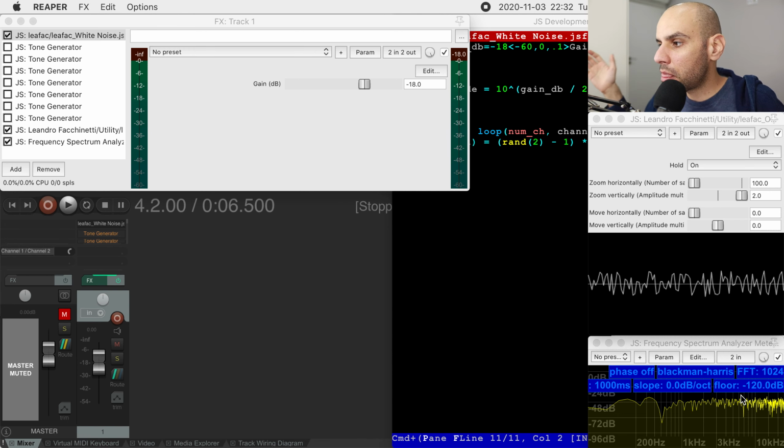So you're burning in your speakers ideally. So it's recommended by some manufacturers, I guess all manufacturers, that you play something that sounds like white noise for 6 to 8 hours in your speakers, and you play as loud as you can. So if you have neighbors, you probably don't want to play as loud as the speakers can because that would be too loud, but you want to play that sound as loud as possible.